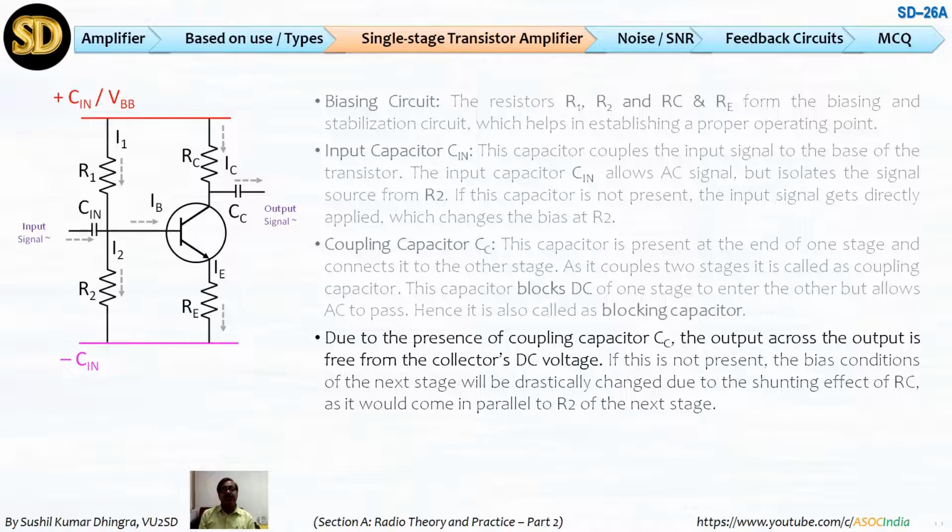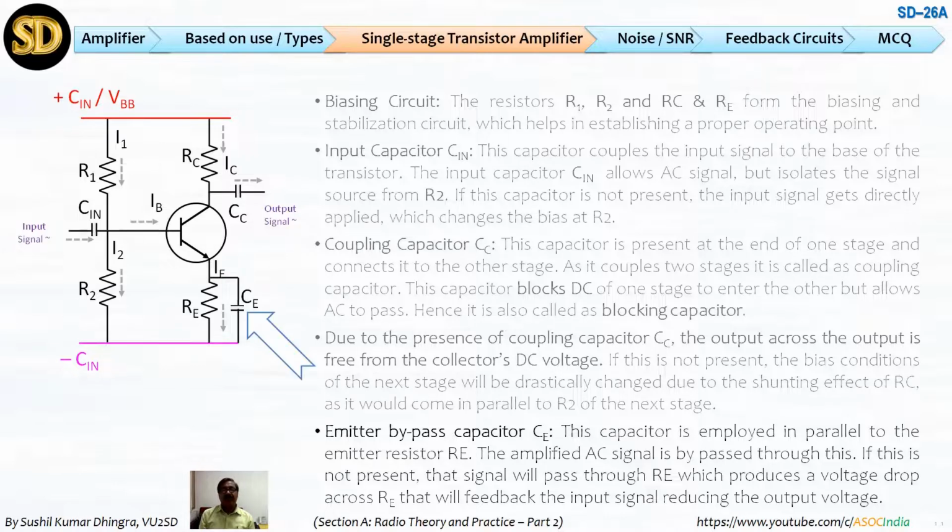So this capacitor gives isolation to the transistor, so that the small, negligible load from the second transistor will not affect the previous transistor. So it is giving stabilization. It is very much needed for next stages. We can also use a bypass capacitor in case of slight variation in frequencies. This CE will bypass the other frequencies so that it gives more stabilization and a better signal, and it is of a very small value. So this one we can also use in transistors.